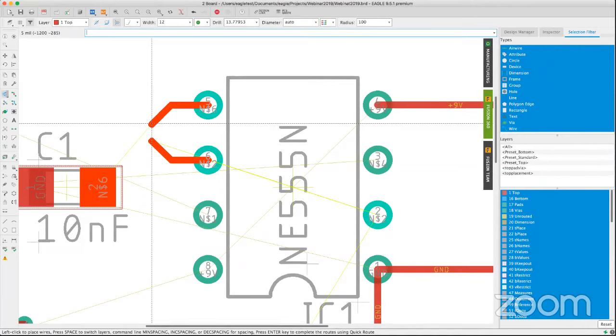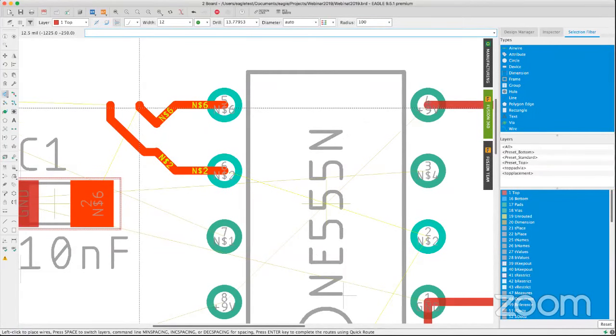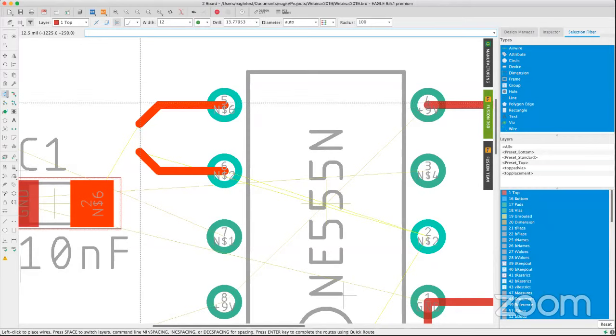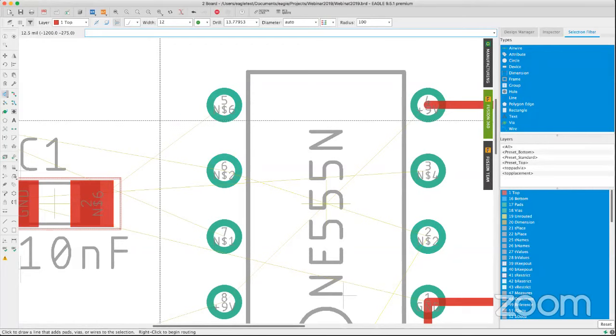Okay. So this is one way that you could use to actually, but this is not differential pair routing, okay? This is not even close to differential pair routing. This is just being able to route multiple lines simultaneously. Very useful if you're in a bus configuration and the lines are just straight across. You only have to do some short bends. And if I'm not mistaken, you correct me if I'm right or wrong, Jorge, I think you could go up to 16 lines at the same time, 16 different signals at the same time. That is correct.